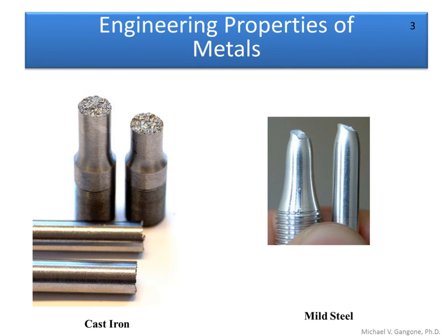Okay, so the fracture zones, as you can see here, will tell us a lot about a ductile versus brittle material. The other thing you notice in this ductile material is that when it failed, or prior to it failing, it underwent what's called necking. You can see in this particular region here and here some permanent deformation that occurred, and the cross section slendered down a little bit. It went from an initial width like you see here down to a smaller width up here. So it necked, as we like to say, at this particular point.